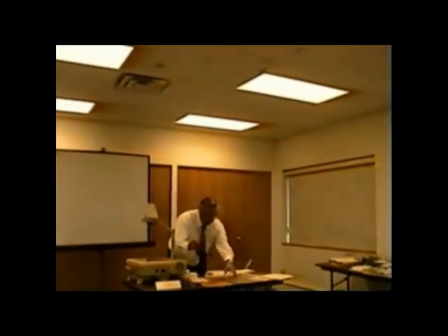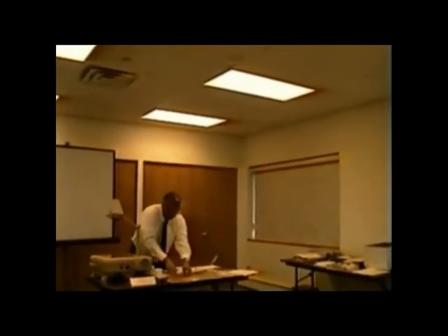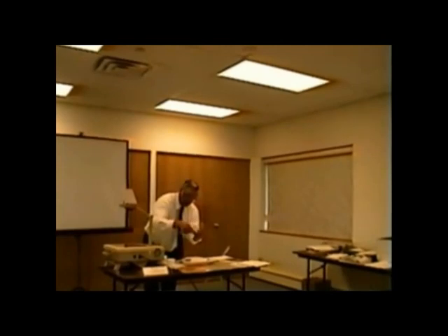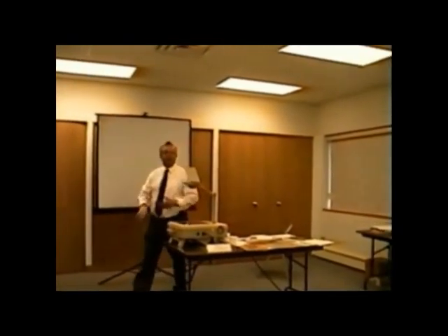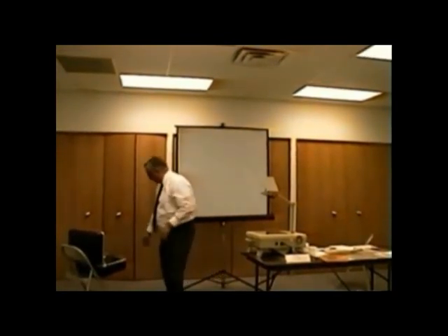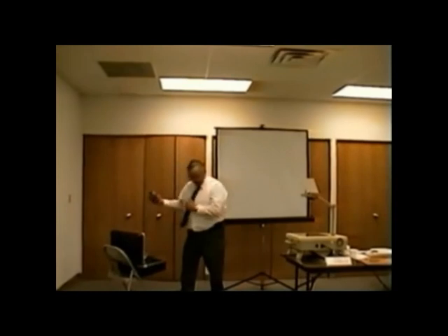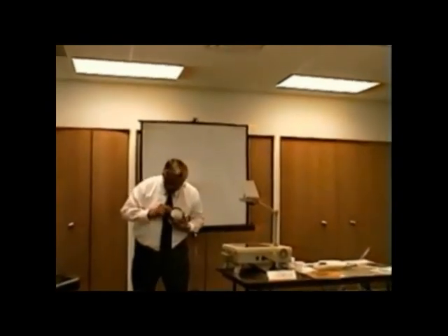Let's talk about gas pressure. All right, let's get rid of some of this. And this. And let's talk here. We expect you to be equipped with some kind of an instrument to check gas pressure. You could use a magnehelic gauge. We're going to be using a magnehelic gauge and showing this to you in a little bit. But this particular one only goes from 0 to 3 inches water column.